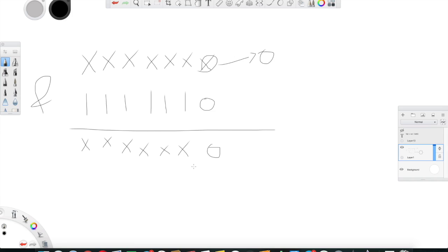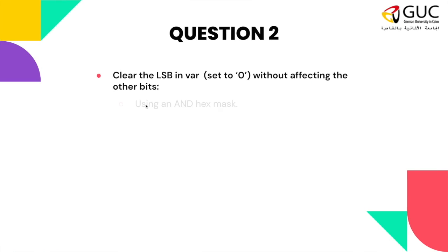So actually this will be represented as, we have here 4 1s, which in hexadecimal will be an F, and 1110, so I'm missing 1. 1, 2, 3, 4, 5, 6, 7. Yeah, I missed a bit at the beginning. Here it is an X, and here it is a 1, and here it is an X. So actually here is F, and here is E. So it will be 0xFE. If we move back, using an AND mask, which will be var equal var ANDed with 0xFE.